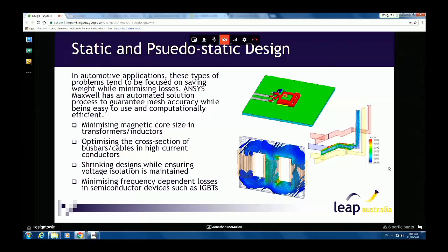So this also applies to PCB designs. If you're designing your own PCB and power supply to fit together as tightly as possible, you tend to have tracks which can be longer than they need to be. So using these types of tools, you can optimize your track lengths to make sure that all of your semiconductors are balanced when they're under full load.